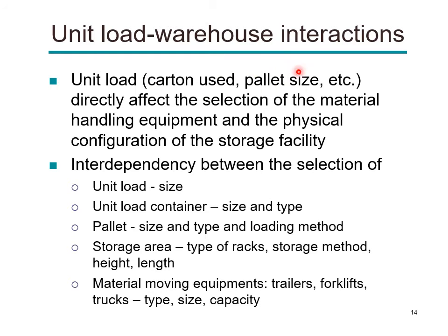The selection of the unit load, for example, the pallet sizes and the cartons used, directly affects the selection of the material handling equipment. So which material handling equipment you are going to use depends on your selection of the unit load. Okay, so that's why these designs should be made carefully. The selection of the unit load also affects the physical configuration of the storage facility. So there is an interdependency between these selections.